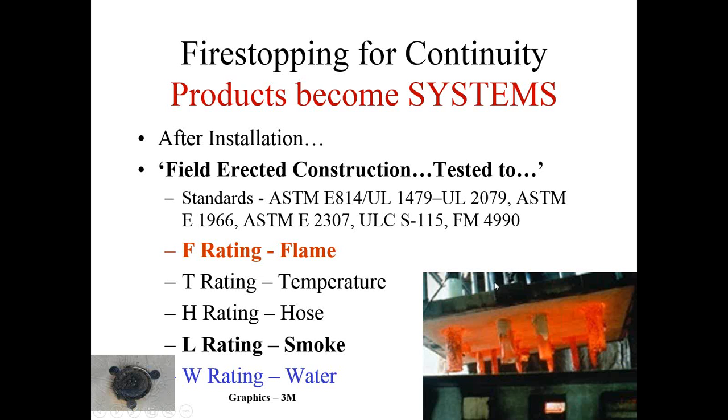Why is that T rating important? What happens if somebody stores boxes, paper goods, plastic gloves, anything that's flammable on the non-fire side of that assembly? If somebody stores something there, it can catch fire without flame ever poking through that assembly.